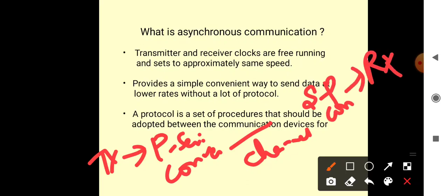So what we are doing is similar to modulation techniques, where modulation is done at the transmitter and demodulation at the receiver. Here also, in order to be cost effective, to reduce the expensiveness, and to remove the disadvantages, that it requires many wires and is used for only short distances, this can be communicated over longer distances by converting these parallel signals into serial signals. So if you are converting parallel to serial, only one wire is needed, instead of, for example, whenever you had taken 8 bits in parallel communication, 8 wires being used.